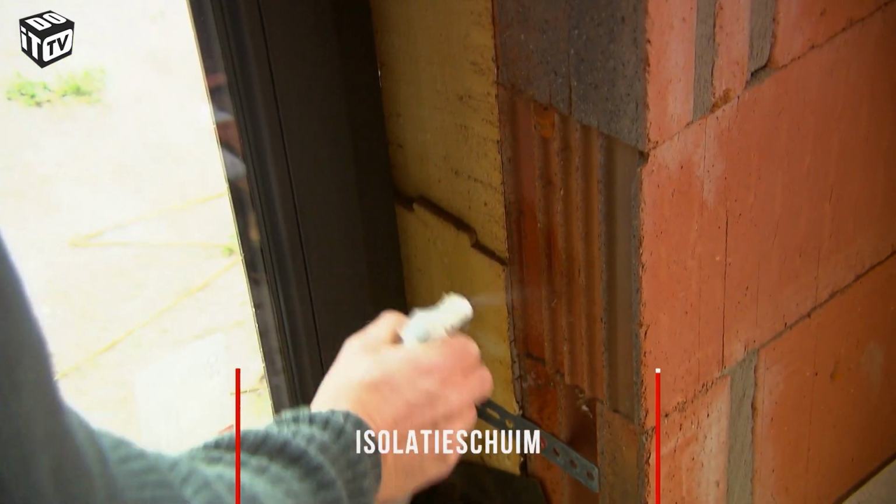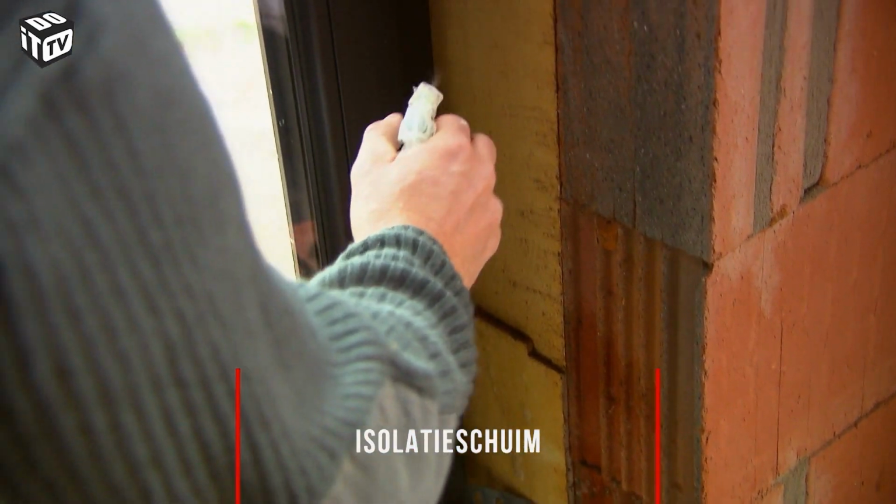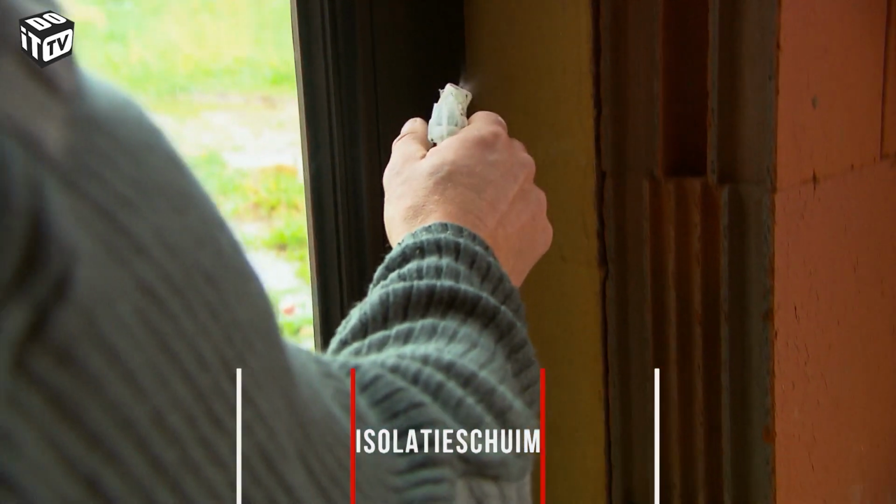The space between carpentry and inner wall needs finishing. For that, just moisten all. We've now lightly moistened the cavity wall insulation, ensuring the PU foam adheres better. We have chosen low expansion blue PU foam for the following reasons. Blue, it matches perfectly with our triple soundproof glass.